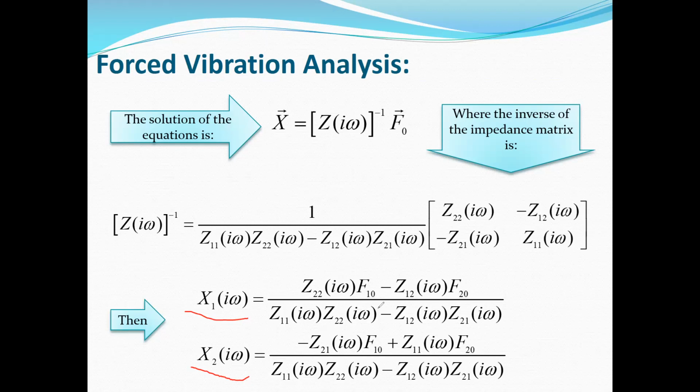But similar to the single degree of freedom system, you know that we will have different types of excitation. I mean, for example, we can have periodic excitation or non-periodic excitation. For the single degree of freedom system, we use different methods such as Laplace transform or convolution integral. And here you will see we can use the Laplace transform as well for the system with 2 degrees of freedom, but this procedure is only applicable for systems with harmonic excitation.